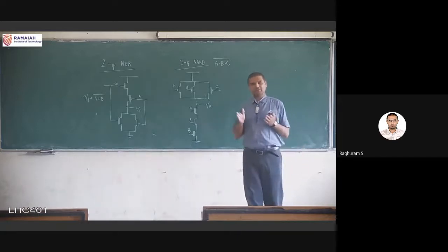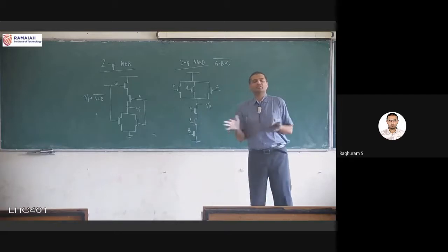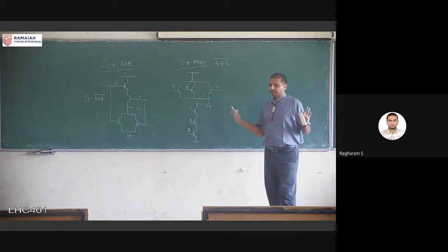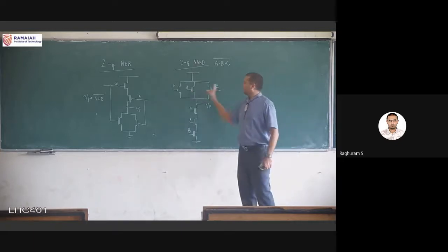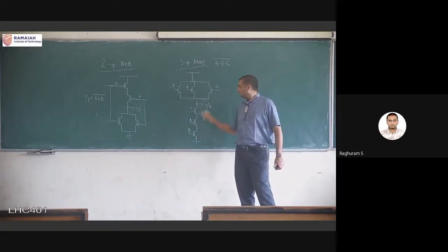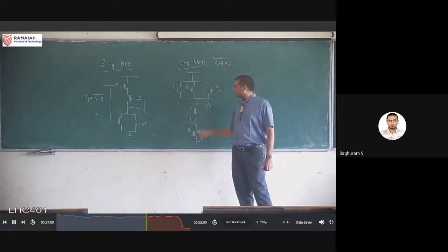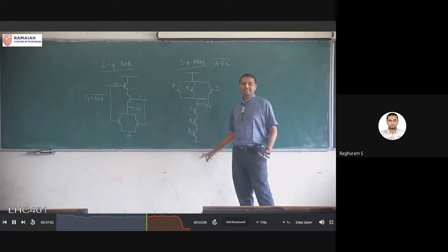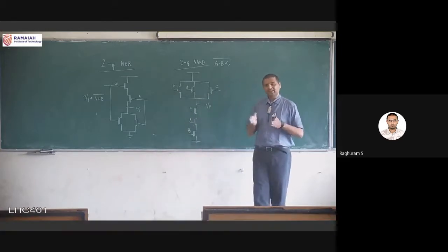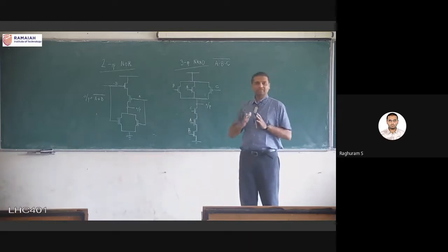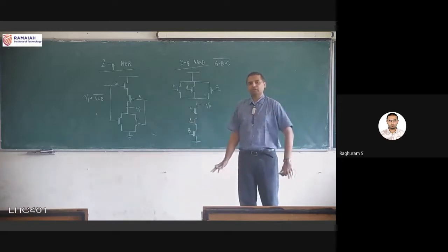The best way to answer is equivalent circuit. Okay, and the answer is it does not matter. You can have the above in any order, the below in any order. The only requirement is these three transistors have to be in parallel, these three transistors have to be in series. As long as you are maintaining that structure, the order of the inputs above or below doesn't matter. They don't have to match with each other also.